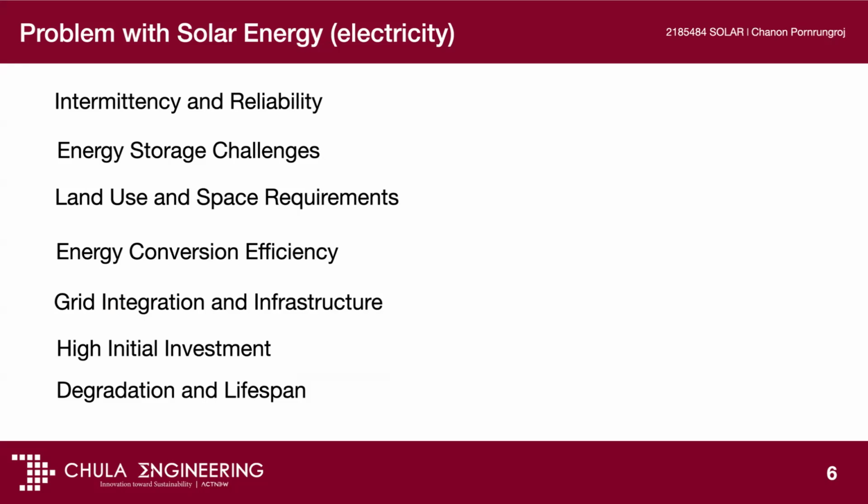And if you imagine you want to store that solar power to be used for industry or for the whole city, it's going to require a large amount of lithium batteries, and lithium batteries are known for catching fire, and heat becomes a problem, especially in Thailand. That's why we don't see much large scale battery energy storage in Thailand, because we have very high heat and you also require cooling to make your battery storage safe.